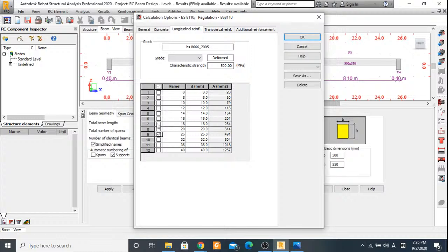Okay, the ratio is small somehow, so I will take large bars of 25 millimeters, and then transversal reinforcements we'll just take as 8, and for additional reinforcements I will use bar 12. All right, let me just use bar 12 for additional reinforcement. Oh no, let me use bar 12, bar 14, and if you like bar 20, 25, be free. All right, so we'll do that.